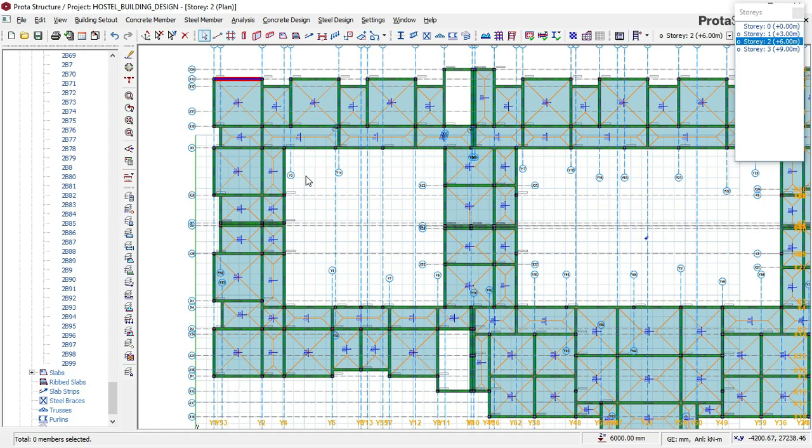So it's always good to add wall loads to your beams, because if you ignore the wall load on your beams, that means you're saying that the building will not be able to carry brick walls, except you want to use partition walls, which are fiber materials, not concrete bricks or blocks. If you're using that kind of fiber material, there is maybe little use for you to insert a beam load and not a wall load. There is a place where you can insert that kind of load, which I'll show you in my coming videos.